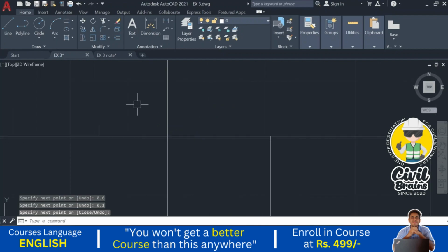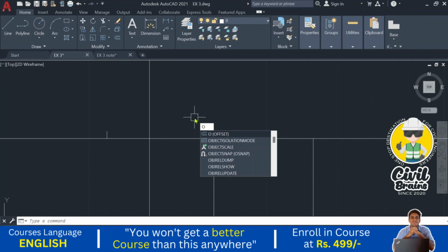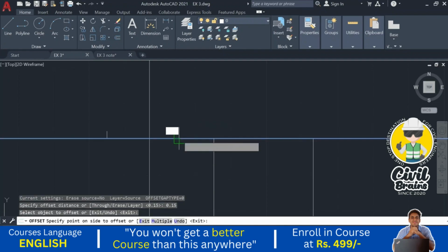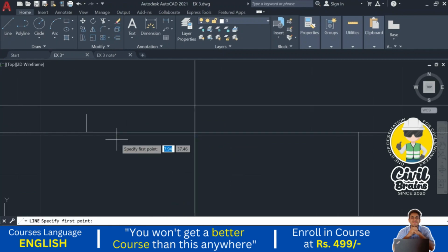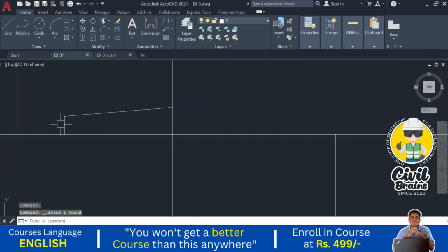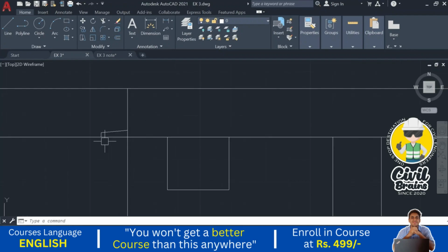And what is the thickness of the chhajja at the start? That is 0.15. Offset 0.15, and from here using the line command I draw this one and join it. Here you can see a slight slope. This slight slope we need to provide so that whatever rainwater falls can be easily drained off. For that purpose, we are providing the side slope here.